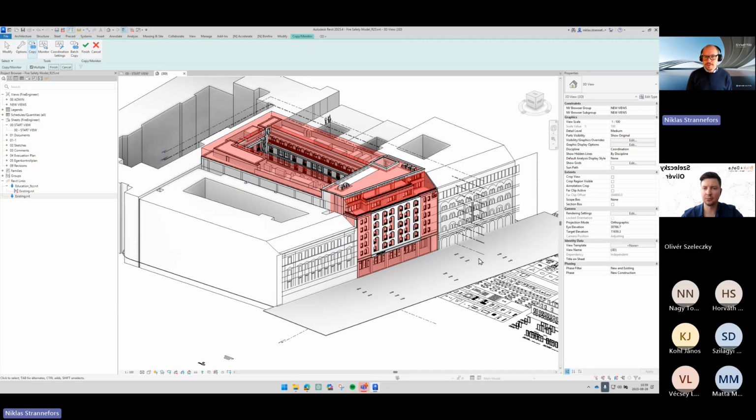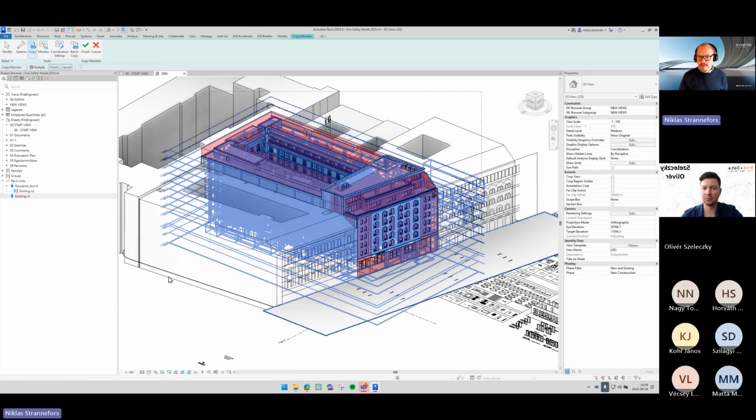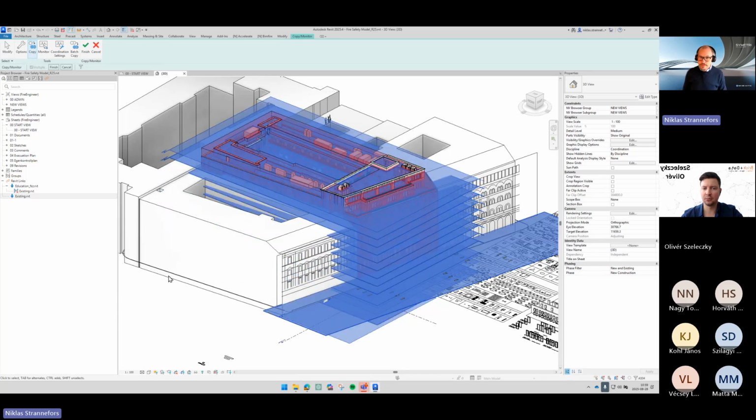Some are not. The architect has maybe drawn some levels within the building, sometimes somewhere else. It's very badly designed. So we're going to do it as if it were very poorly designed. Just go from right to left and hold down your left cursor. That means we will select everything that the box touches. So we're going to get a lot of things like this. It's going to load and it's going to be heavy, and it's going to grab a lot of things. But now we make sure that we have, quote unquote, most levels, even if they were within the building and, quote unquote, poorly designed.